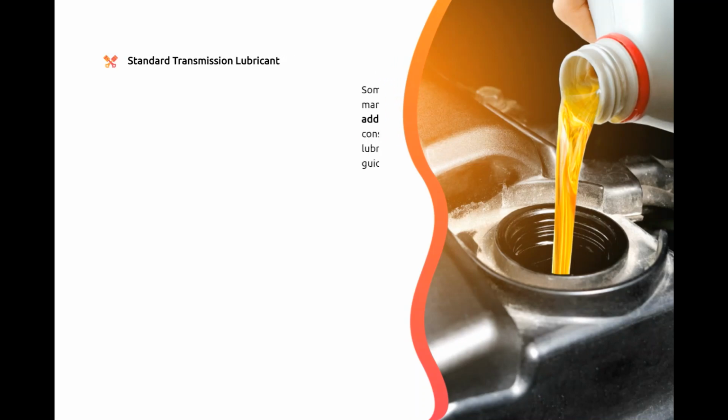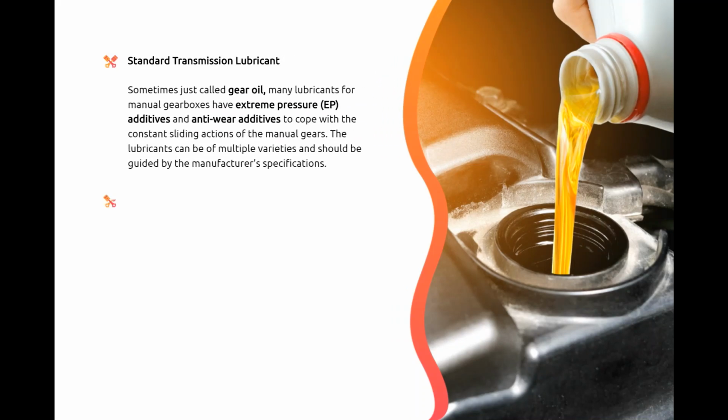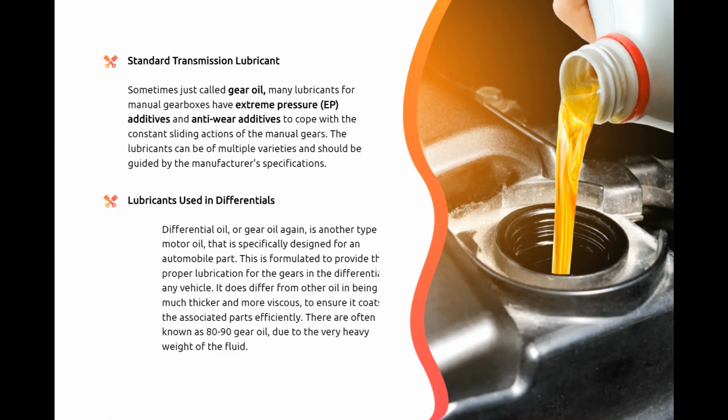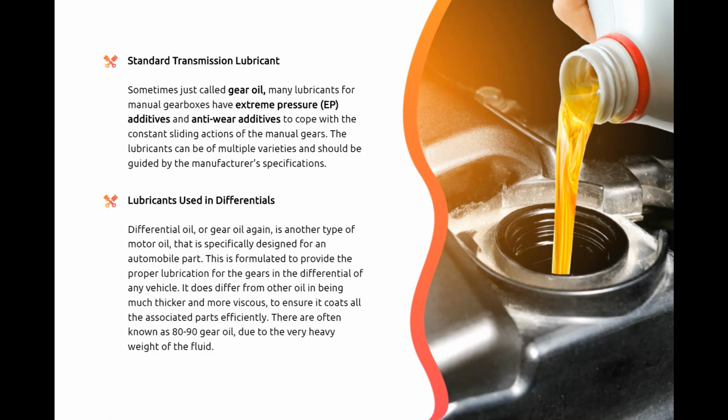Standard transmission lubricant. Sometimes just called gear oil, many lubricants for manual gearboxes have extreme pressure (EP) additives and anti-wear additives to cope with the constant sliding actions of the manual gears. The lubricants can be of multiple varieties and should be guided by the manufacturer's specifications.